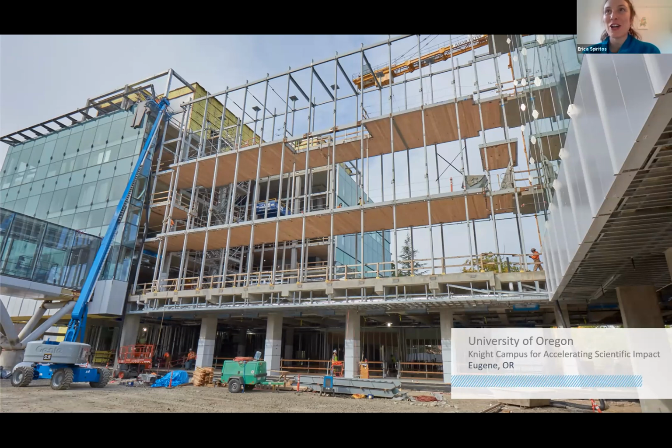Okay, so I just wanted to show a number of hybrid structures that might just get the wheels turning about some of the considerations when timber interacts with other structural materials like steel or concrete. So in this case, you're looking at a timber connector bridge between two adjacent structures utilizing steel supports. You've got steel posts and then a steel angle that's supporting the CLT panels. And the major strength axis of those panels is across the width of that connector.